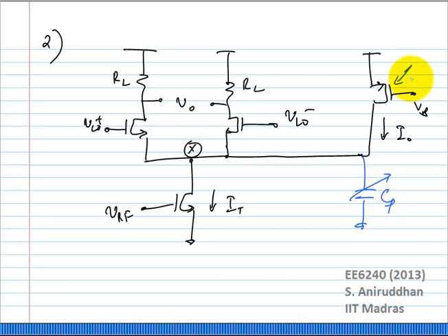And a second effect is that by reducing the GM of the switching pair, by reducing the current through the switching pair, you are reducing the GM LO, correct? What effect does that have? The time constant at this node was a function of the GMLO. It was related to CP over GMLO. Okay, so you have actually increased the time constant of charging and discharging of that node.